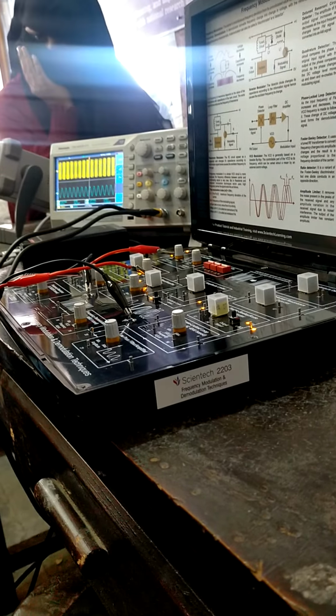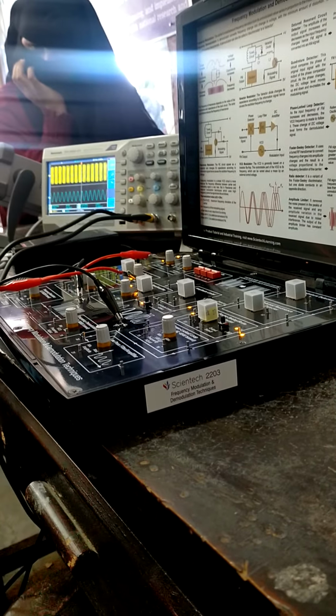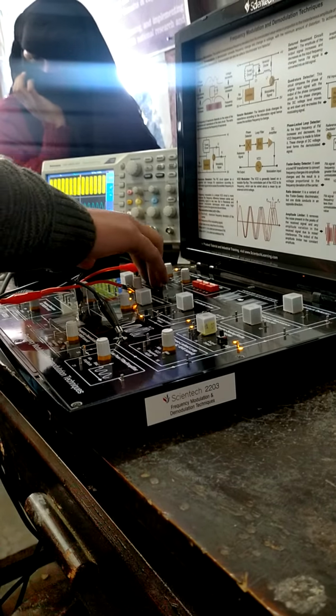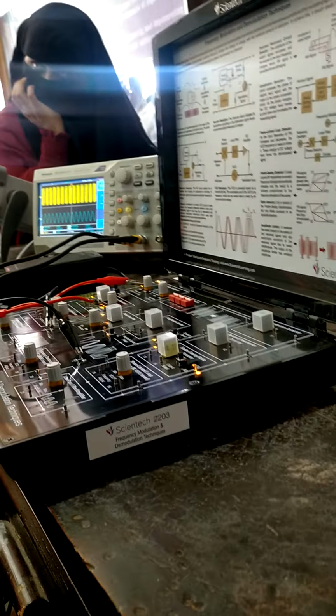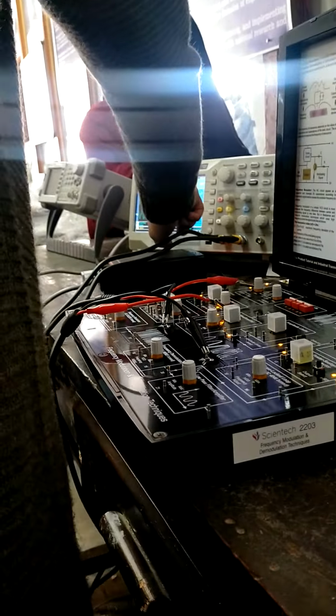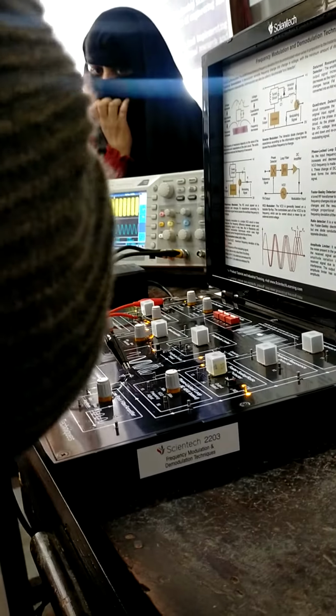Okay. So for example, in this experiment, what you have to do first, you have to observe the FM modulation process. You have to first observe your audio signal, note its frequency as well as its amplitude. Okay, this is the audio signal that I am giving, message signal or the modulating signal. So after that, you will utilize a reactance modulator in order to generate the FM. Now there is a toggle button here in order to select which type of modulator you want to use. Okay, there are 2-3 modulators here. You can use any of them for generating your FM signal.